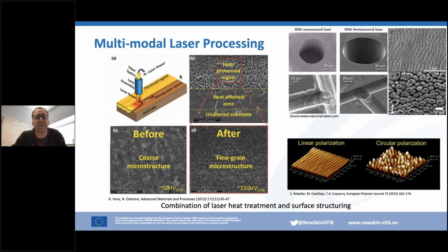Through the application of this thermal energy, we can have a recrystallization of just the surface to alter the surface microstructure, which leaves a very small process region on the surface while not altering the bulk material itself, which leaves the bulk properties intact while allowing things like surface hardening to take place.